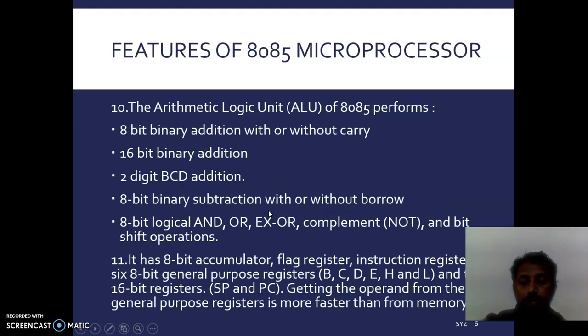Coming to the next feature, it has an ALU which performs operations like 8-bit binary addition with or without carry, 16-bit binary addition, 2-digit BCD addition, 8-bit binary subtraction with or without borrow, and logical operations like AND, OR, XOR, NOT, and bit shift operations.